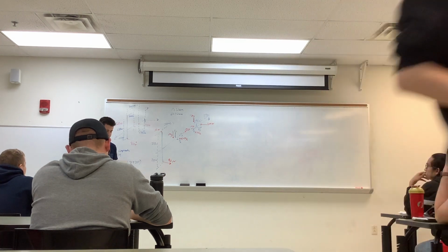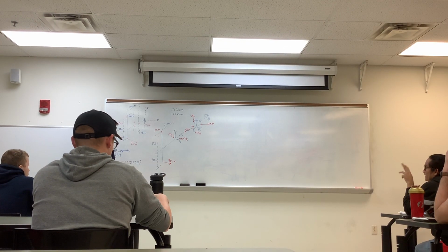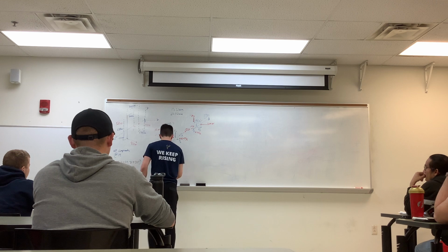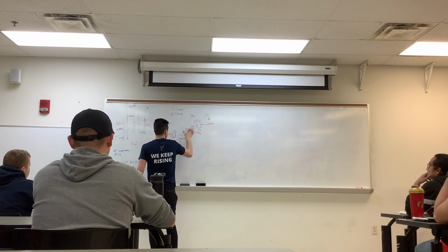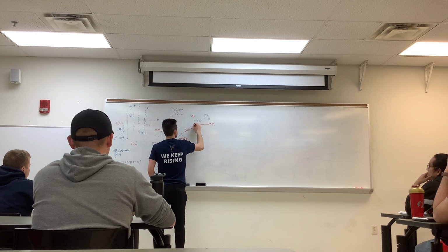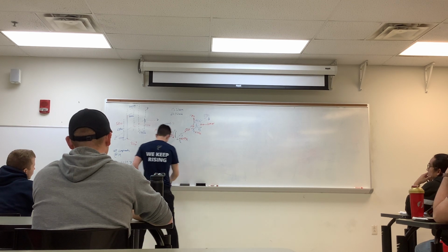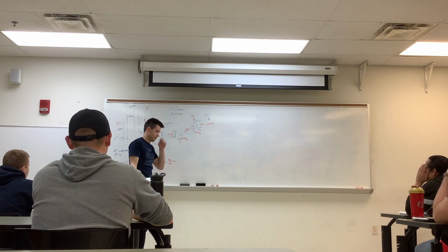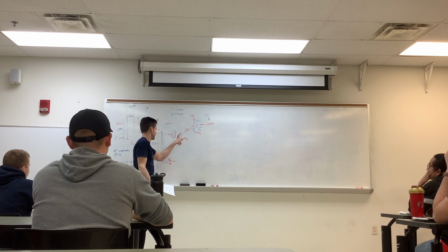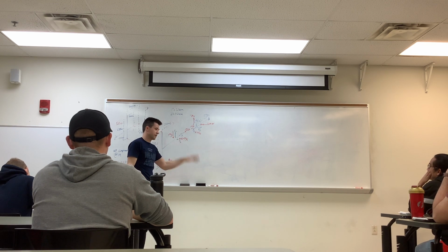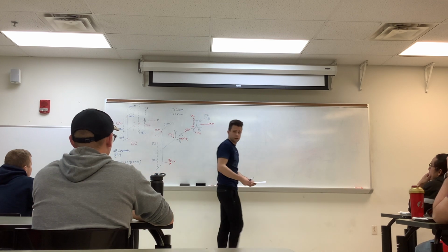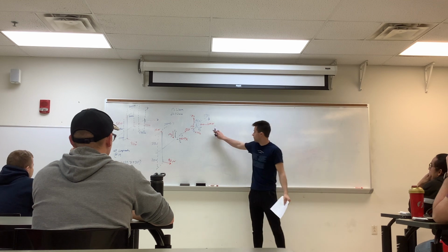Are the directions of the moments in both diagrams going down? You have one in each. This one should be up. They should oppose each other: one in the x, one in the z, moment about y. On the exam, it doesn't matter which direction you have them, as long as they're opposing. Typically, the axial force, or the force coming out of the cross section, will be pulling away from it. And then the corresponding Fy and Fx just need to be opposing themselves on the corresponding side.